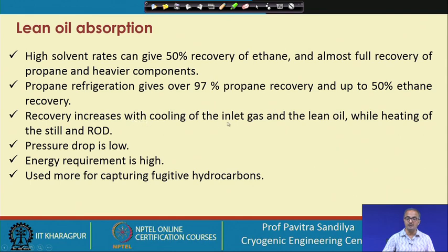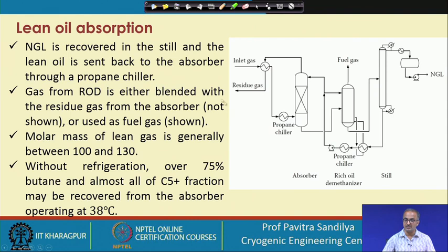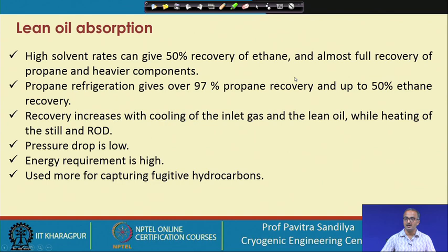Recovery increases with cooling of the inlet gas and the lean oil, while heating of the still. We have seen that the inlet gas is being cooled and the lean oil is also being cooled, as we have seen from here, that the inlet gas is cooled and this lean oil is also getting cooled through these liquids here. So both these things are getting cooled, so that we can increase the recovery.